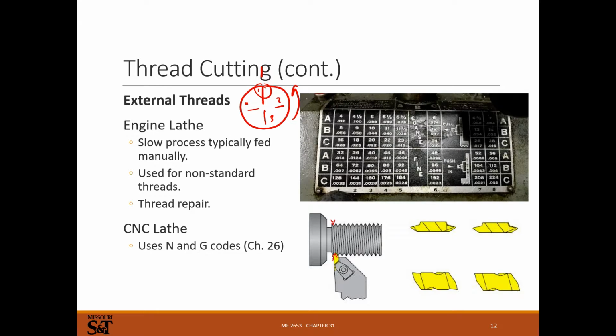You're going to disengage your power feed, or disengage the clutch. You're going to move this thing back out and then get down to the next depth, and then you need to re-engage. It's the half nut, what that's usually called, but you need to re-engage this clutch when it gets back to the start at 1. If you engage at one of the other starts, it's going to machine phased off, and it completely ruins your threads, and you've got to start over again.